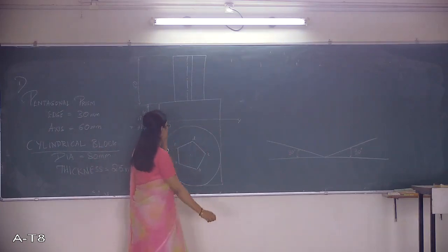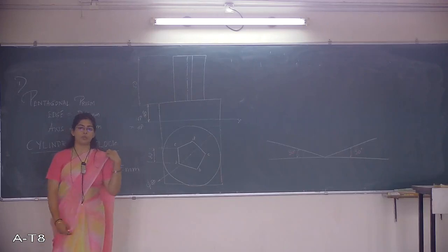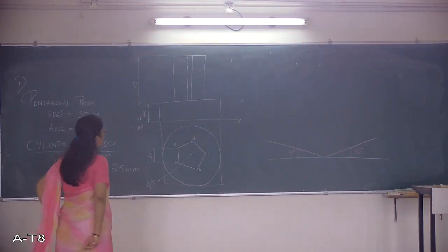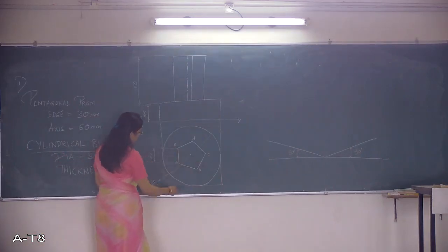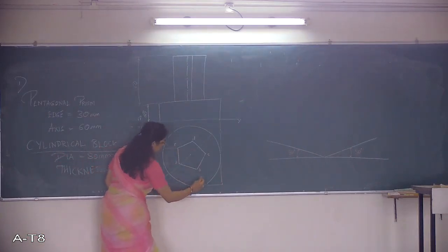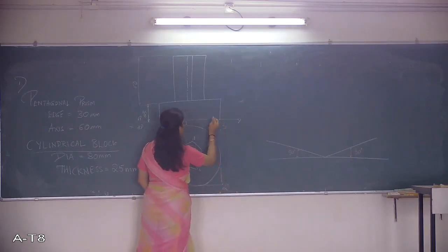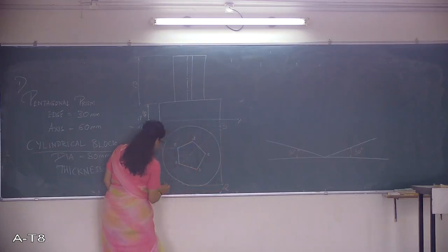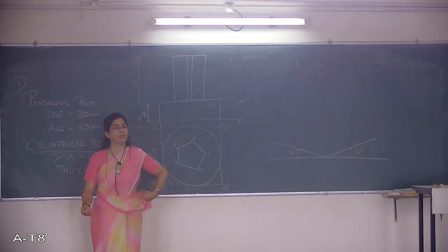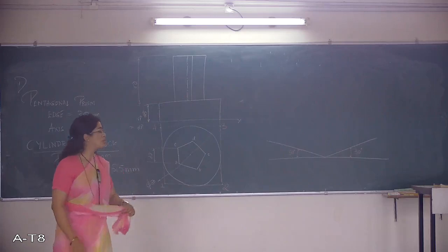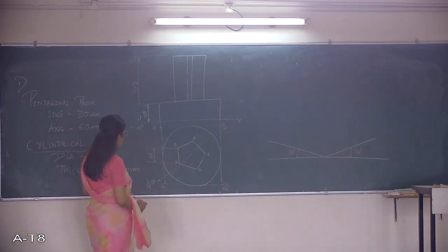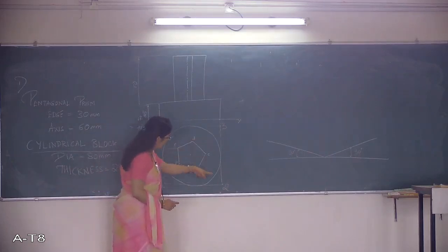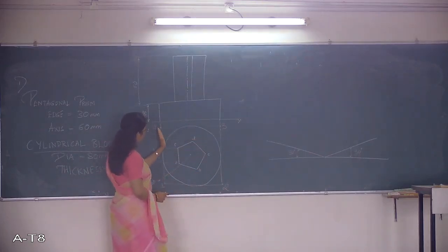Put this into a box, and whenever you're putting it into a box, for every solid you'll have to do this. You have to put all the solids in the boxes, and once you put this in a box, you number the box, 1, 2, 3 and 4, the 4 corners of this box. Now this box need not always be a square, it can be a rectangle as well. Okay, so it need not be a square, you just have to enclose that solid into a box. So first I have enclosed this cylinder, the top view of the cylinder, into a box.